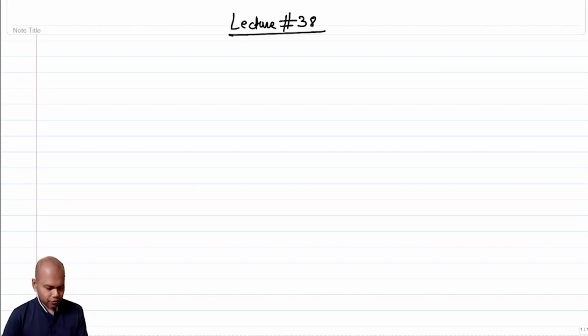So up until now, if you recall from lecture 1 to lecture 37, we have spent considerable amount of time and covered considerable amount of ground, covering various aspects of RFIC design. We have talked about what are the metrics of importance in RFICs. For example, how do you calculate noise, how do you evaluate noise, sensitivity, distortion, and several other metrics. We talked in fair amount of detail how a receiver architecture looks like. We spent considerable amount of time optimizing some blocks, for example, LNA, different types of mixers.